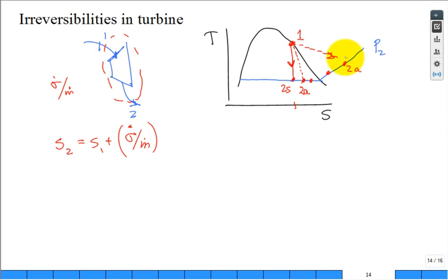So we're going to have an eta subscript t, which is a fraction. It's a measure of the efficiency of that turbine. We were introduced in Thermo 1 to the isentropic efficiency. That's what we're talking about. It's a ratio of the work that the turbine produces for 2 cases, and it always is less than 100%.